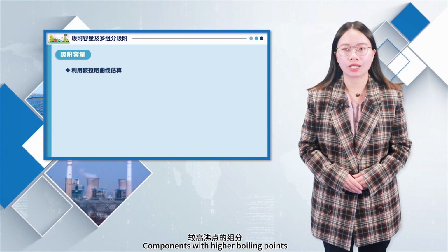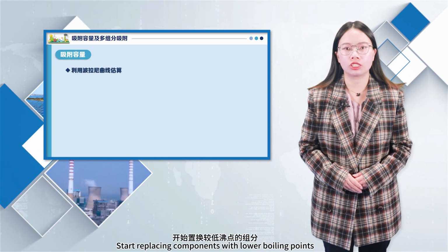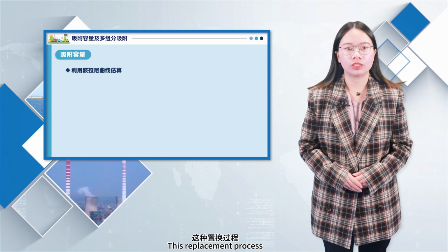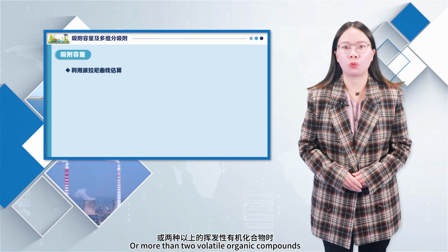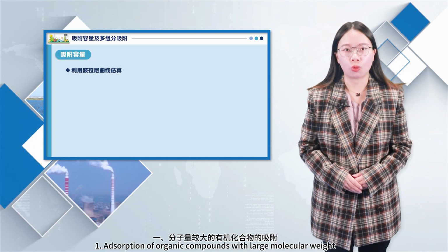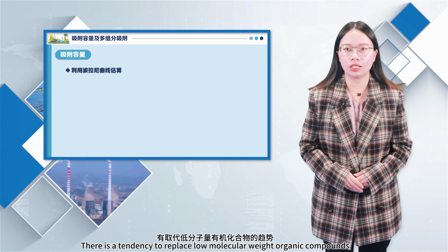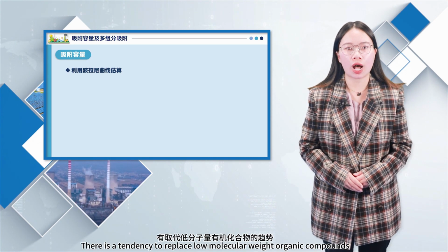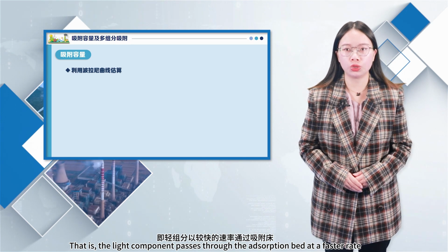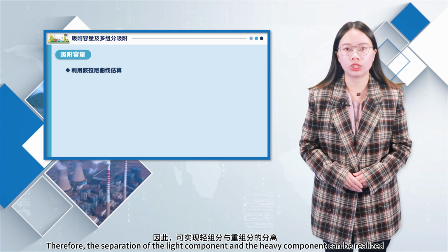At this stage, components with higher boiling points start replacing components with lower boiling points, and this is repeated for each other component. In this replacement process, when there are two or more volatile organic compounds in the airflow, adsorption of organic compounds with large molecular weight has a tendency to replace low molecular weight organic compounds. That is, the light component passes through the adsorption bed at a faster rate. Therefore, the separation of the light component and the heavy component can be realized.